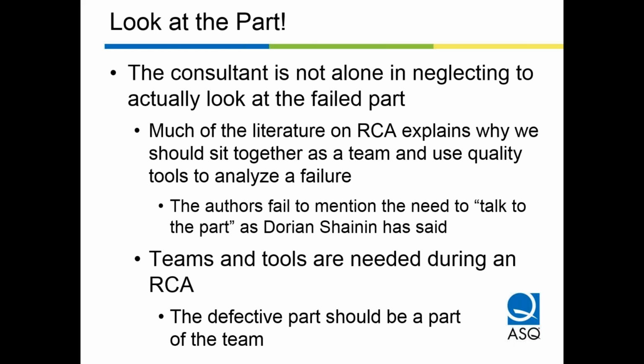Maybe that thickness is related to the failure. By design, it should have been thicker. That's not information we could have gotten if we only discussed the part. Imagine, nobody's ever seen the failed part, and we're brainstorming ideas. I'm not knocking brainstorming, sometimes you need to do that, but the empiricism, look at the part. That's why I'm talking about empirical root cause analysis, and I unfortunately do see a need to discuss that topic.